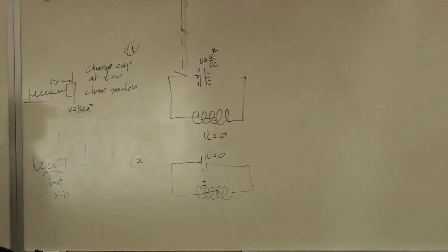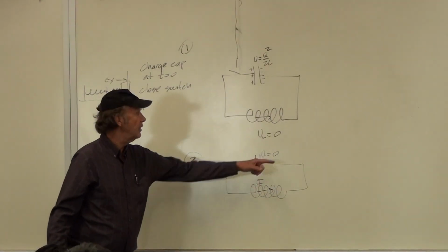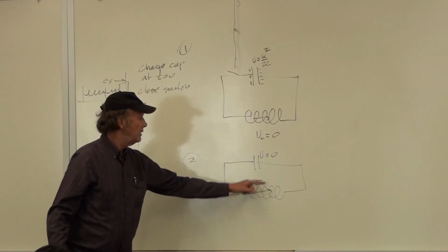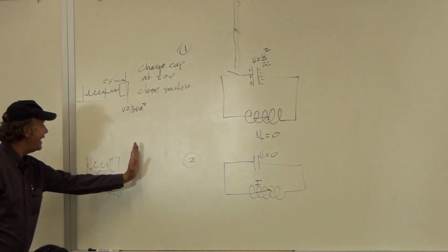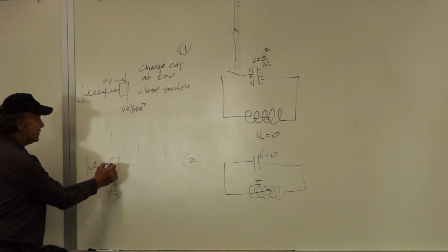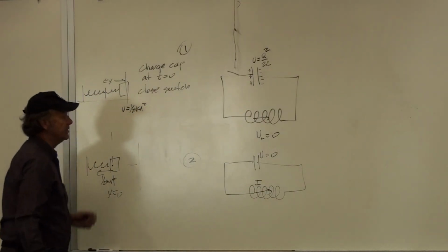And so it's not going to just give that energy up. It's not just going to suddenly go to 0 because it's not being driven anymore by the voltage across the capacitor. When it reaches that point, it has what we call inertia, because it doesn't like change. Just the same way as a mass doesn't like change, this current doesn't like change.